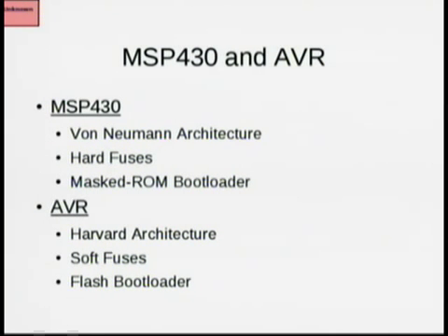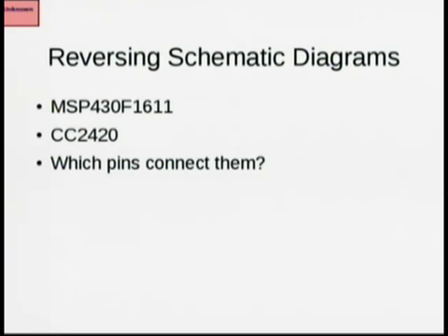But on the MSP430, it's just as easy as in those mid-90s articles on writing stack overflow exploits. You just overflow the return pointer and you make the return value a piece of RAM. Further, the incoming packet is always stored at the same address, so you can be rather certain of where you should jump.